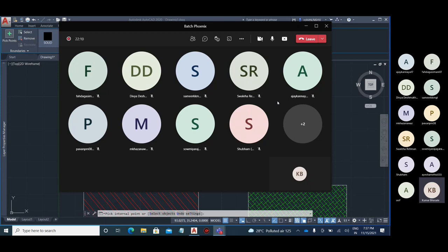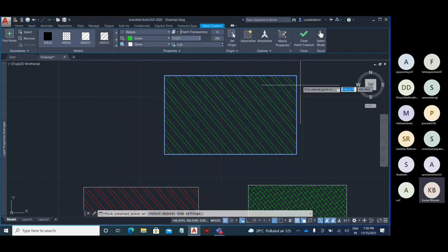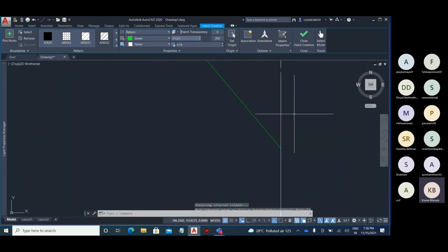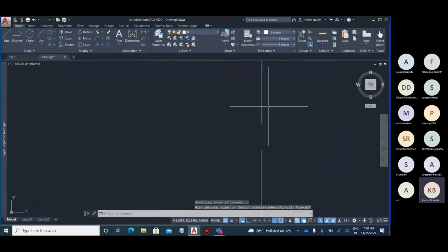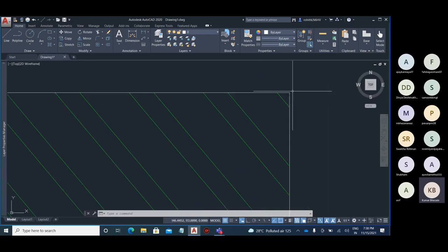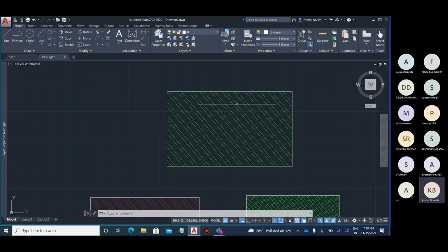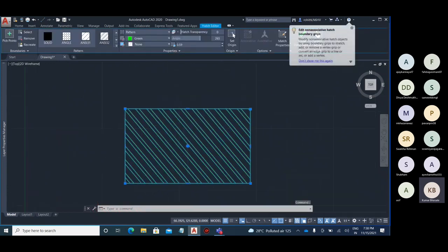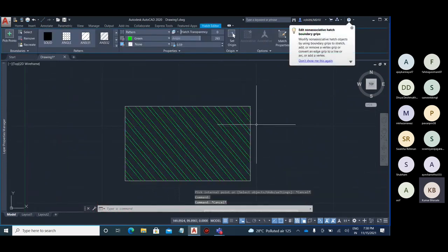So let's say up till 500 is okay, but beyond that you can create it. So below 500 don't consider it. Like this type of things are there. So let's say over here I gave 500 value. If the gap is more than 500, then don't give it. But if it is less than 500, create the hatch pattern. So this kind of gap tolerance option is over here. That is your gap tolerance.